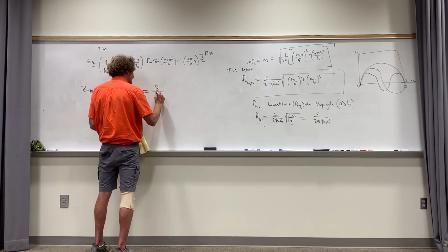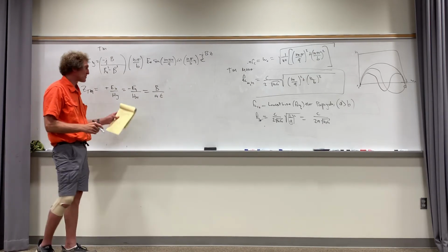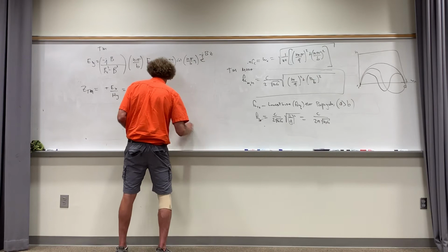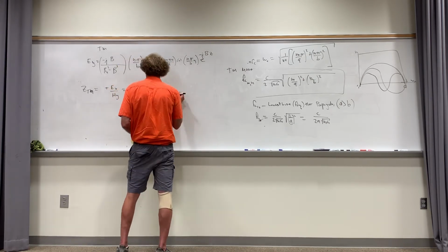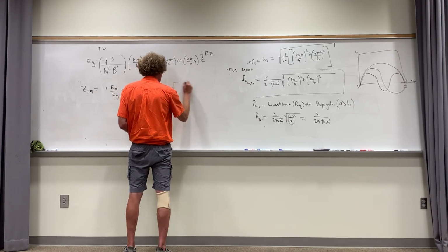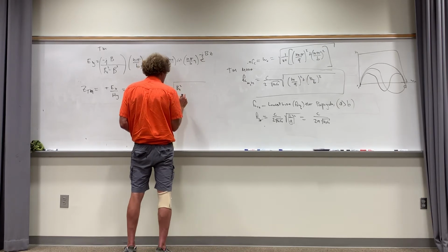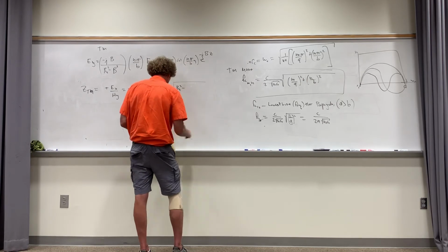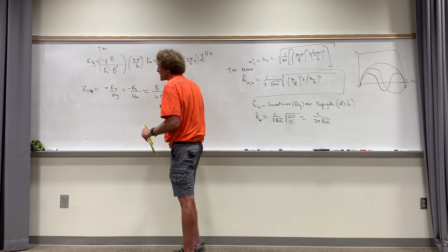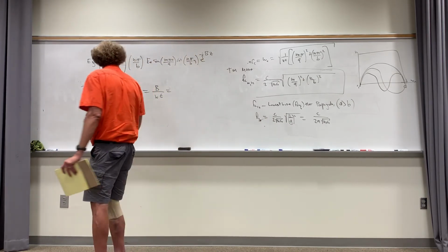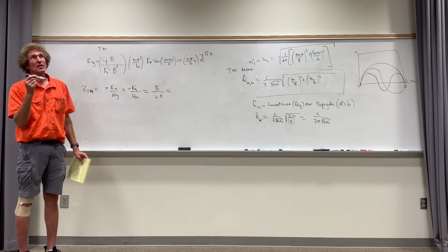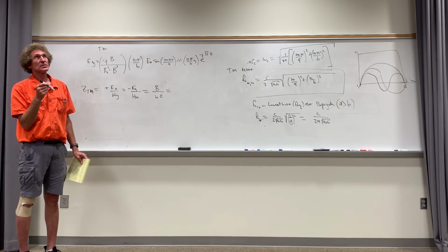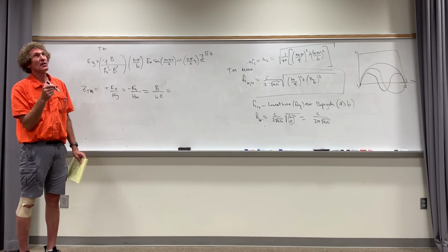And when you do all that, you can thank God you get this. It's beta over omega epsilon. Now that beta is the beta we just found out about. That's omega, by the way, omega epsilon. Well, beta was equal to the square root of beta unguided squared minus, well, I'm going to stop for one second. This beta unguided is like k, and it's the square root of beta unguided squared minus kx squared, which is m pi over a squared plus n pi over b squared.